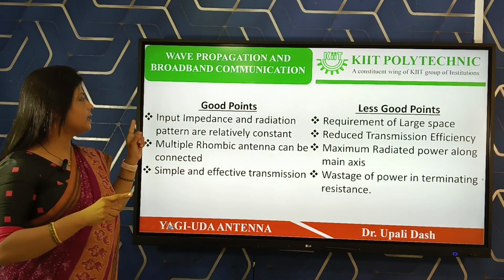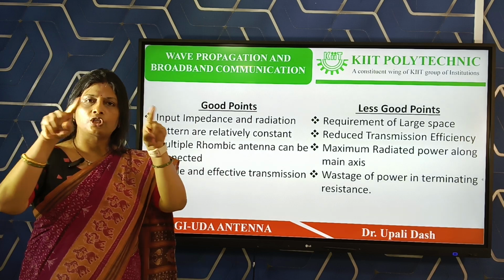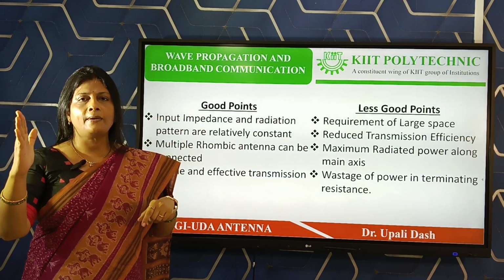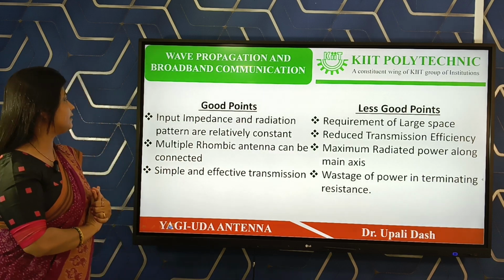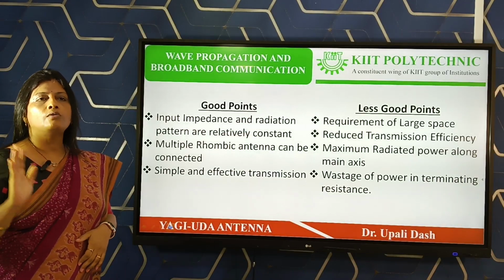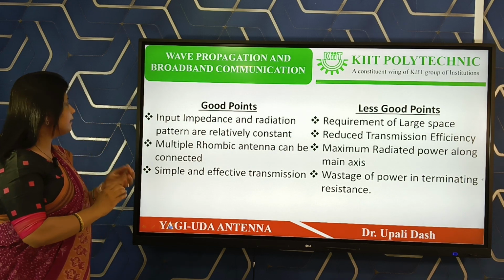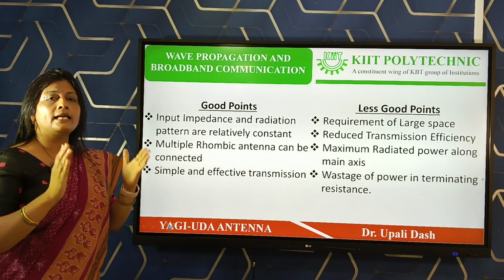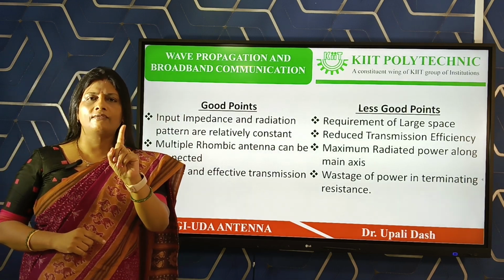So here in the rhombic antenna, this is a great advantage: automatically, due to the structure of the rhombus, the input impedance and the load impedance are perfectly matched. That gives a better directivity and it is constant. It doesn't vary with the variation of frequency.